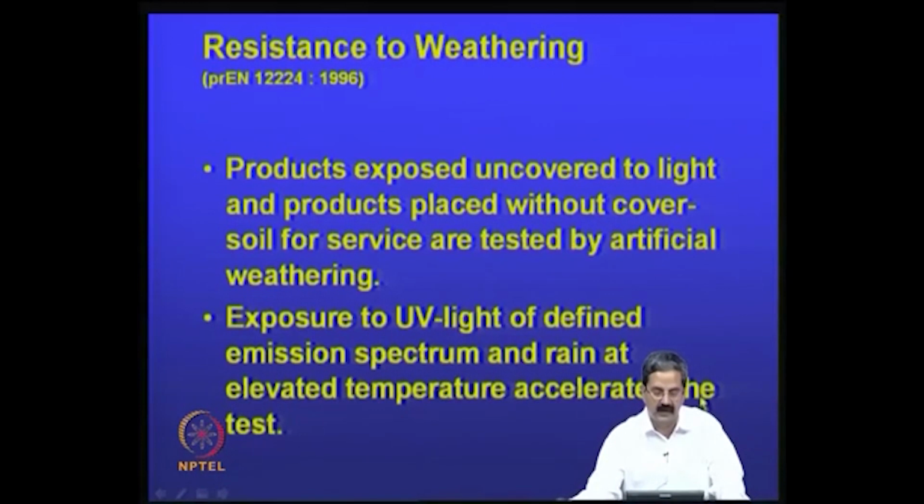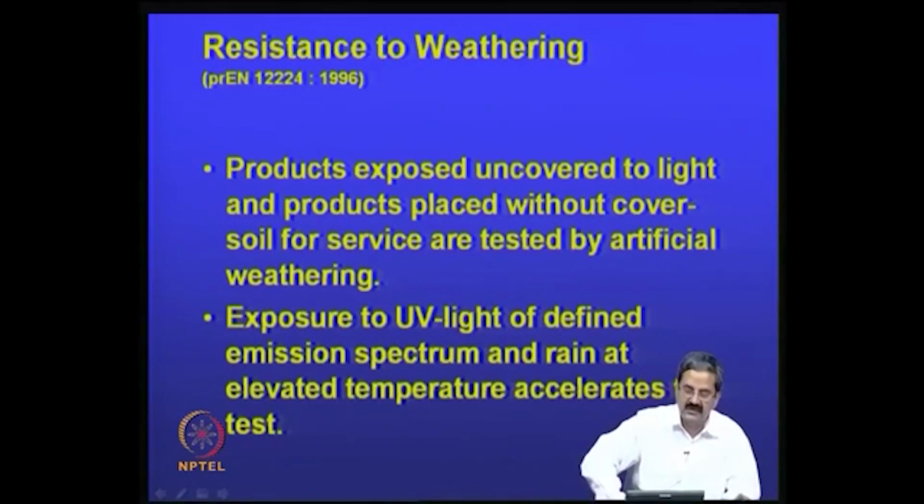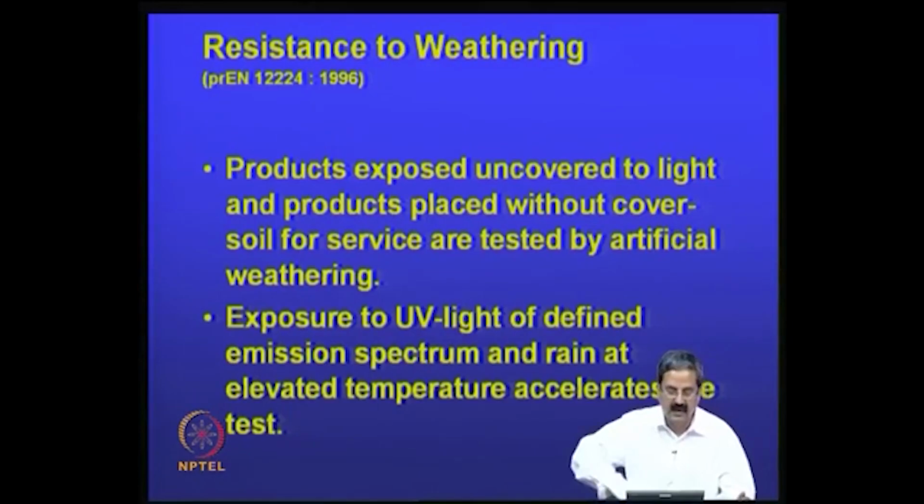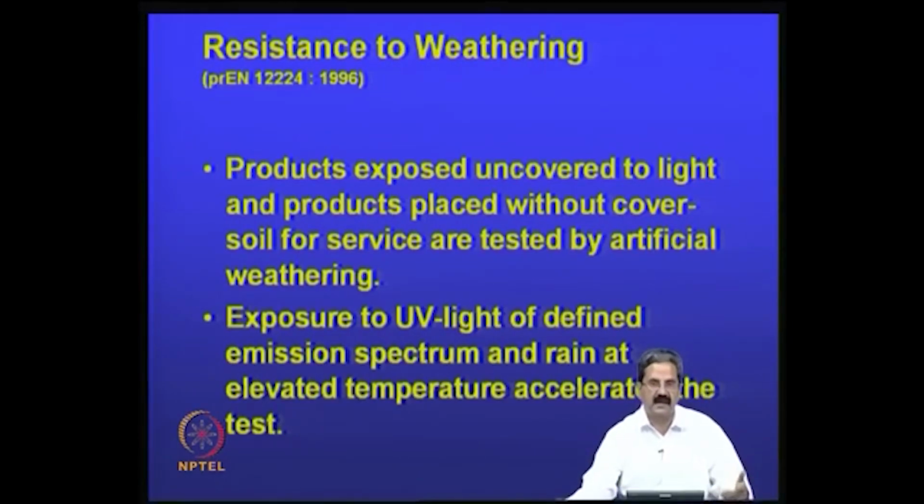Okay. So, resistance to weathering, what is that? It is essentially that the products are exposed to uncovered light. If you do not cover them properly, the possibility is that they are exposed to ultraviolet rays. I have seen, you just take a geosynthetic material and leave it outside. Initially it is nice, but after that, because of the ultraviolet rays exposure, whatever the sunlight exposure, it gets very stiff and all that.